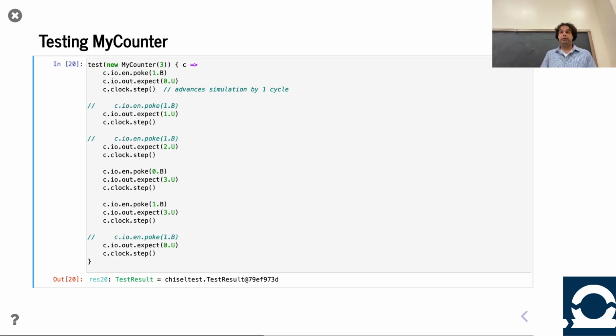Now, if you're writing pure Verilog by yourself, this is exactly the same, right? If you're writing pure combinational Verilog, it is effectively instantaneous. If you are a register, it does take a cycle. Now, where Verilog starts to show some differences are things like a negative clock edge. Well, these are positive registers, so you're not going to see that.